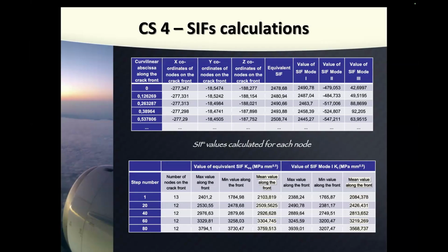In aviation, one cycle is one flight. We call it ground, air, ground. So you have takeoff, you have flight, and then you have landing. And it was supposed to be replaced after 10,000 cycles, according to the manual, and it was at 9.5 thousand cycles when they checked the records. So never do that, when it's very close. So they said, okay, we have time. We still have 500 flights.